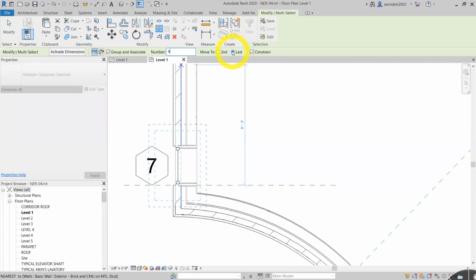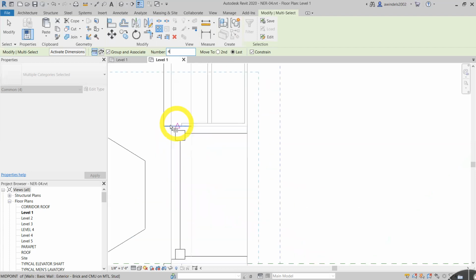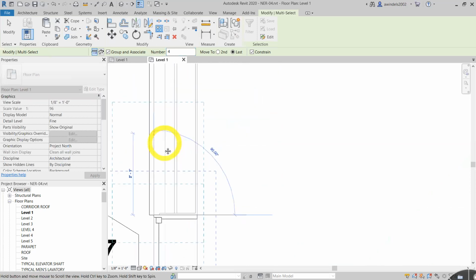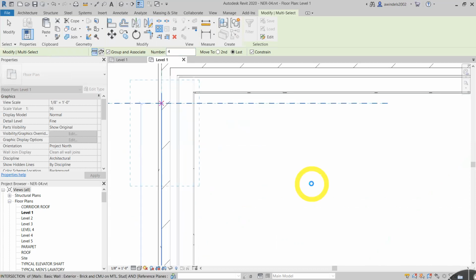We have to be pretty surgical on our points. Now it says where we're going to use our points of the array. So this part's a little tricky. You got to pick the exact 2 spots. So we're going to pick the top of the window and then the reference plane we just created. I'll show you in a second. So pay close attention to the picture on 190. And this will be our first point. This will be our second point. It'll take a minute to think.